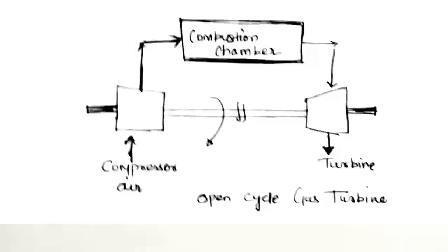Again, the other kind of power plant is the gas turbine power plant. In the gas turbine power plant, you will be burning some kind of fuel and hot gases will be generated, and these will not be used to heat the water in a boiler using tubes to produce steam, but the gas itself will be thrown on the turbine blades. The hot gases flow on the turbine blades with high temperature and pressure, and using the nozzle, it is possible to convert it to velocity, and whenever that is done, the turbine will rotate and electricity will be produced. So that was the gas power plant.